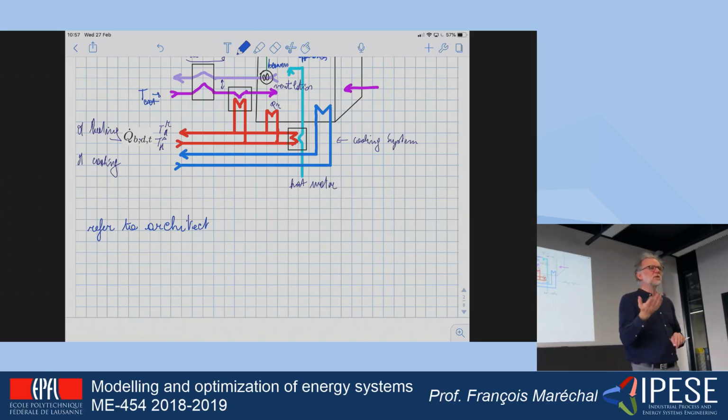So what is also varying in a building like this one? Occupancy? Like who is using it, how many people? Yeah, the number of people. Each one of us is radiating 100 watts, and we are around 60 here, so it's already 6 kilowatts of heat.